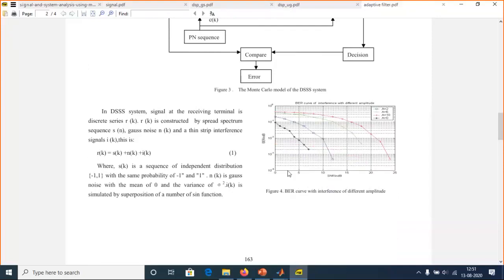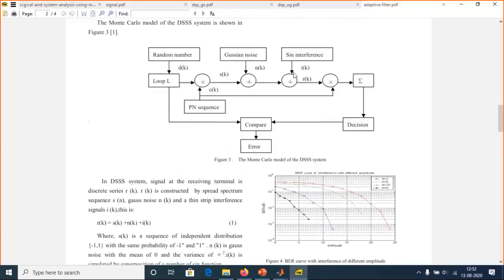And this is how the bit error rate looks, right? As there is an increase in the signal to noise ratio, we modulate signals with different parameters and try to find out the error rate. Here, for example, I have a signal with specific parameters. What this means is, as my noise signal increases, you can see that the bit error rate is also increasing a little bit. Right, so 10 power minus 2 means for every 100 samples, I have roughly 2 to 3 bit errors. So it depends on the signal to noise ratio, and that is what we'll be verifying here.